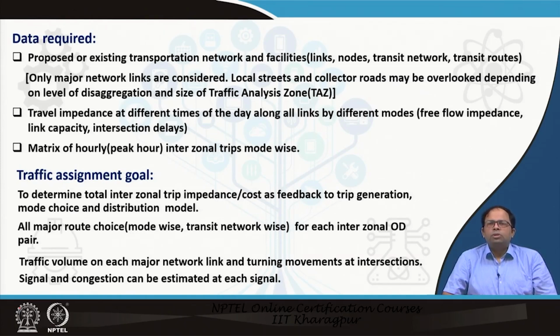For example, if I am choosing a road between 2 points, if I also think about the smaller collector streets or even the local streets in between two zones, then we will end up with many route choices, and all of them would be near to the shortest path. So there is a chance that people have to be assigned to all these routes equally.